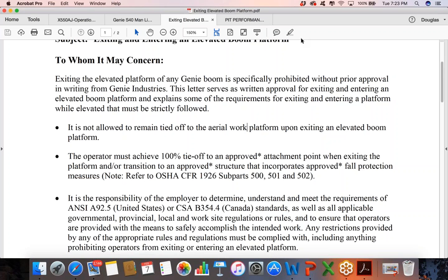Well, we know footwear is going to be basically our leather boots, right? Steel toe and in good shape. Okay. Especially if we're doing arc welding, making sure, and we shouldn't ever have the steel caps exposed because they have a significant risk of electrical hazards and conductivity. And bottom line, it violates the ANSI standard, folks. That cap, we either have to have the boot with a new cap on it, or the initial cap that came with it must be in good shape.